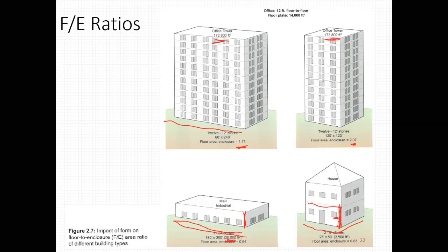And if you're aware of the fact, or maybe some of you have heard of thermal stratification, hot air rises, right? So depending on your ventilation design, if you've got vents coming up from the floor, then you're going to have layers of warm air that will slowly rise, and it's going to be comfortable down here. But if your ventilation is up here and you're having to push air down, then it's not going to be as effective, right? Because hot air is less dense than cool air. So hot air wants to rise because it's more buoyant than colder, more dense air.